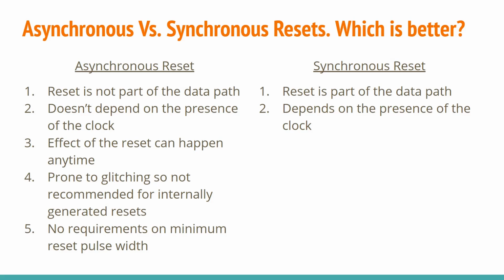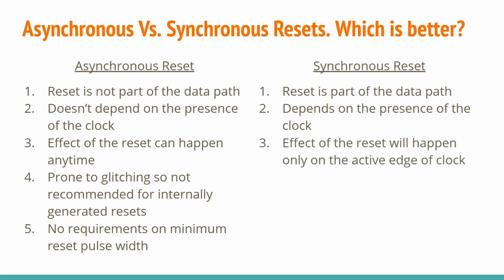Let me recap this one more time because this is a very important distinction. In case of asynchronous reset, you can reset the circuit even in the absence of a clock, whereas synchronous reset is dependent on the presence of clock for resetting the circuit. Let's move on to the next one.